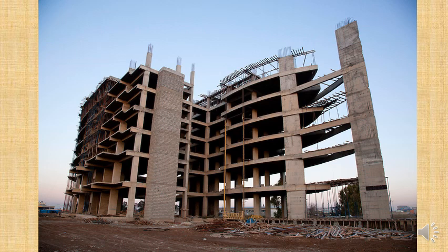The building is being held up with the concrete columns. However, we don't want to add too much weight to the building, because the heavier the building is, the higher the load there will be on those columns at the bottom. So using cinder blocks instead of concrete blocks is a way of reducing the entire mass of the building.